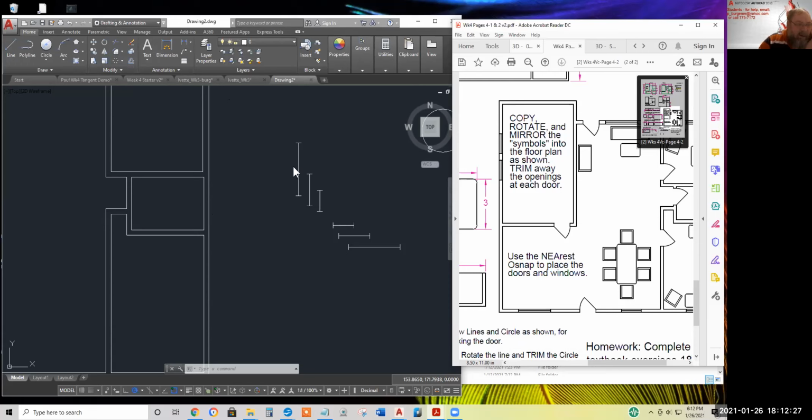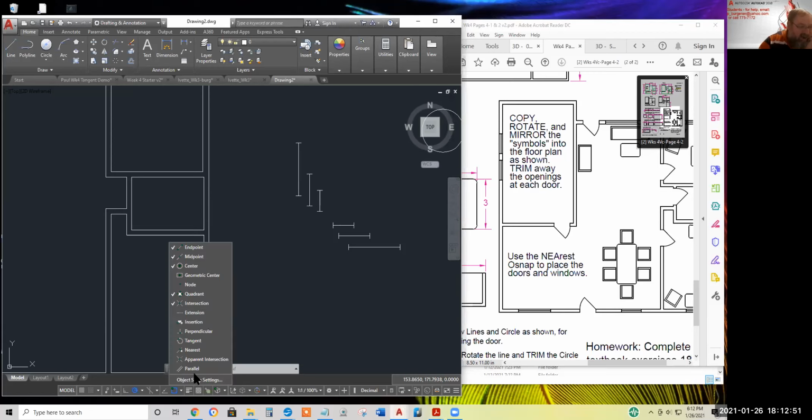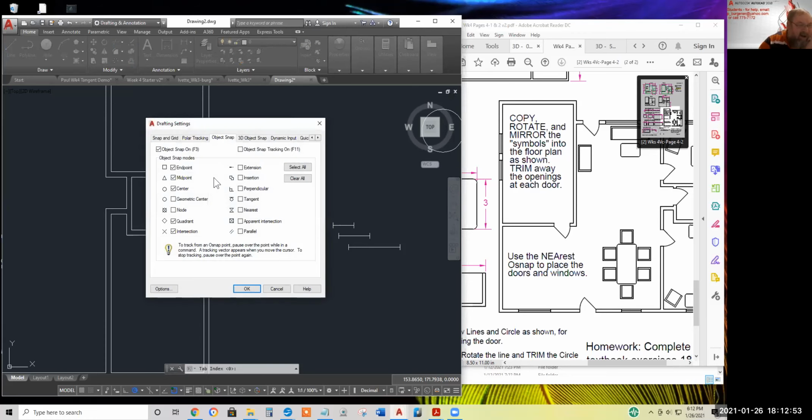Grab it at the midpoint of that line and O snap it at the midpoint of this line. But let's just kind of eyeball it using the near O snap to place our copies. Or better yet, we'll grab it at the end point and use the near to place it. I think we can change our 5 favorites to end and near without regrets.